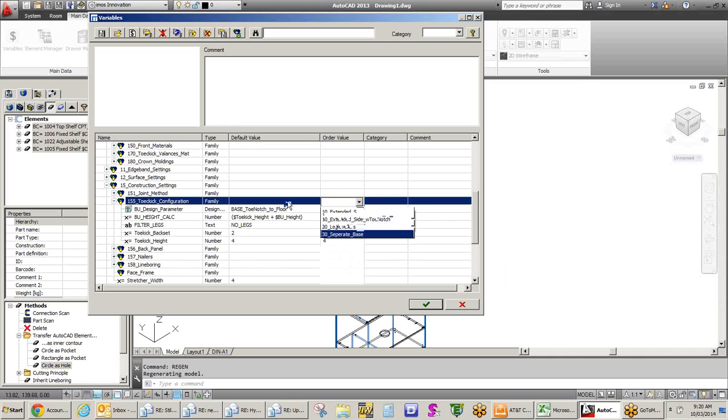Yeah, if I wanted to modify the library for the default values, I would change it in this field, and then I would save that and give it a name. The cool thing is, you know how you could have multiple specification groups in Microvellum? Well, you can have an unlimited quantity of those, which is literally both the materials and construction together. And so you can just say open, go select the one that you've pre-built, and it's just a little dinky file, and it's going to work with whatever the library is built for.